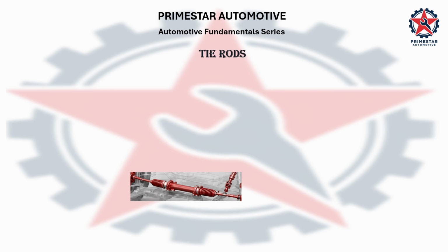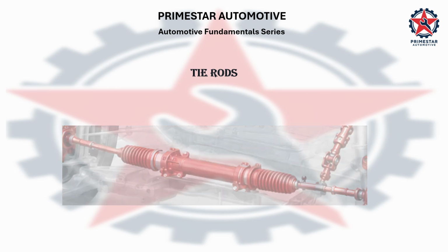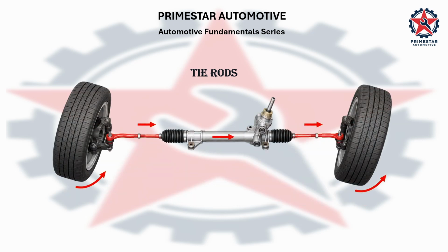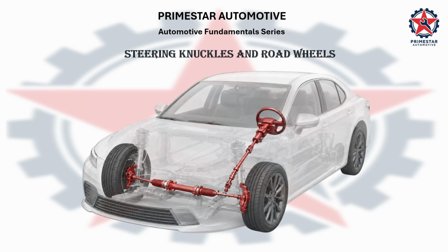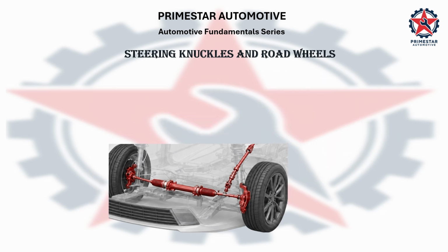Tie rods are connected to both ends of the steering rack. Each side includes an inner tie rod and an outer tie rod end. As the rack moves, it pushes one tie rod outward while pulling the opposite tie rod inward. The tie rods connect the steering rack to the steering knuckles at the road wheels. Each outer tie rod end connects to the steering arm on a steering knuckle through a ball and socket joint.